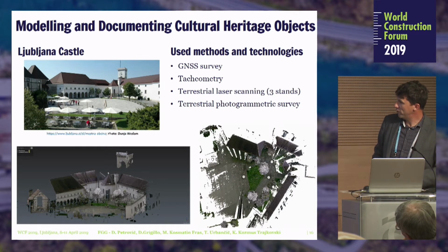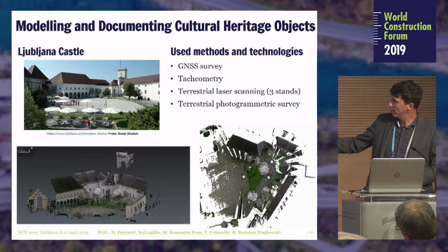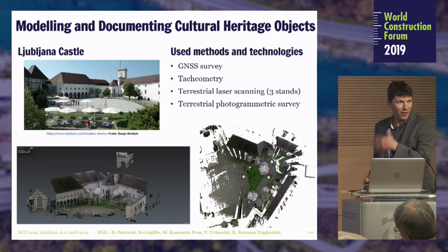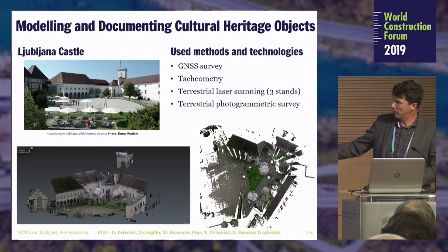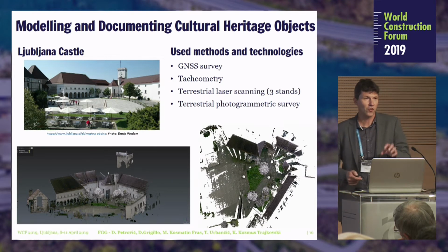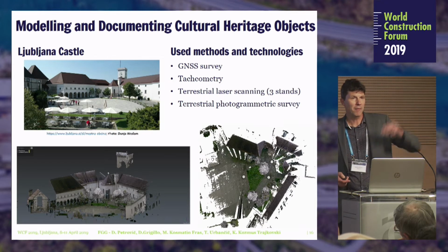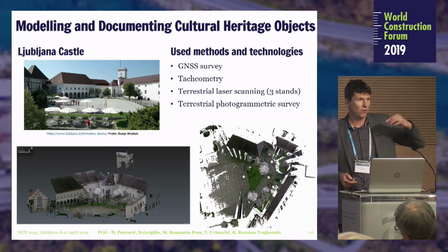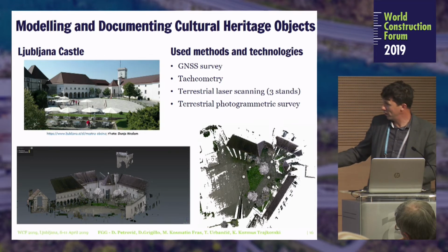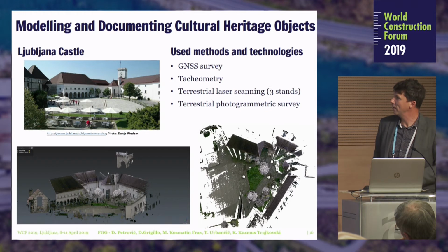Here we can see now the differences when we are using terrestrial laser scanning, compared to photographs. We have a lot of parts where we have a lack of data because we cannot position the laser scanner in so many places, like making photographs from a UAV, for instance. From a UAV, you can take a photograph from every single point, but here we are limited only to the stands of the laser scanner.